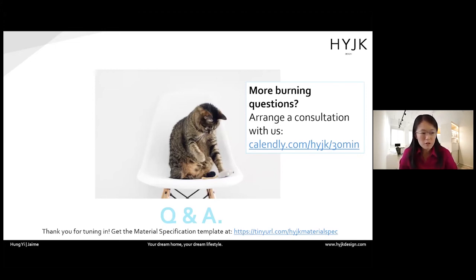Matte and feels powdery. You can check with your developer to see whether that's actually supposed to be the finishing product. Is it supposed to be a matte look or a polished look? Most commonly, it's a polished look, especially for the living area. But sometimes people may want to use a matte look because the matte finishing will be less slippery than the very glossy finishing. So you might want to check with your developer just to be sure. If it's meant to be matte, then that's fine. But if it's meant to be glossy, then you can raise a defect and they can come and help you do the polishing.